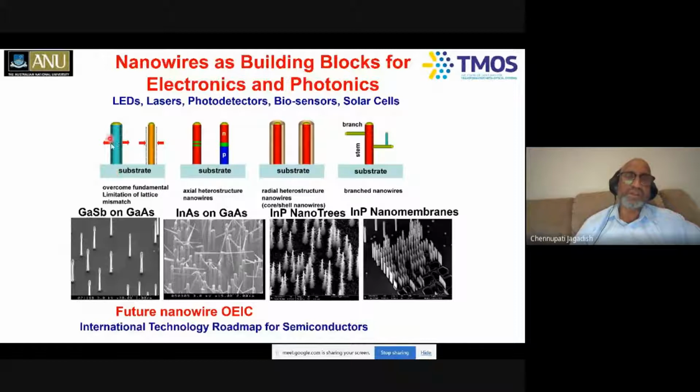So those materials are useless as far as optoelectronic devices are concerned. But with nanowires, because of their nanoscale and three-dimensional nature, they can either expand or contract depending on the lattice constant of the material with respect to the substrate, without creating dislocations in principle. That is a property we are trying to exploit, for example to integrate the 3-5 semiconductors with silicon, which has been the dream for many years, but defects have limited the performance of these devices. Our hope is that by using nanowires, we'll be able to bring both silicon and 3-5 semiconductors together. We and many groups are working in this area.